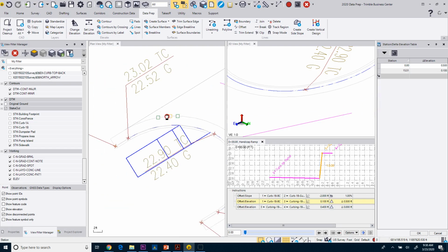Now, I still need to come back and put something over here, because right now it's going from a half a foot to a 1/10, putting a taper all the way through. Now I need to back this out 4 feet, because I know that I'm coming up a half a foot, and I want a 1/10 reveal, so my difference there is 4/10. So what I'm going to do is I'm just going to come in and put in 11, basically minusing 4 from the 15, and I'm going to make this 0.5.